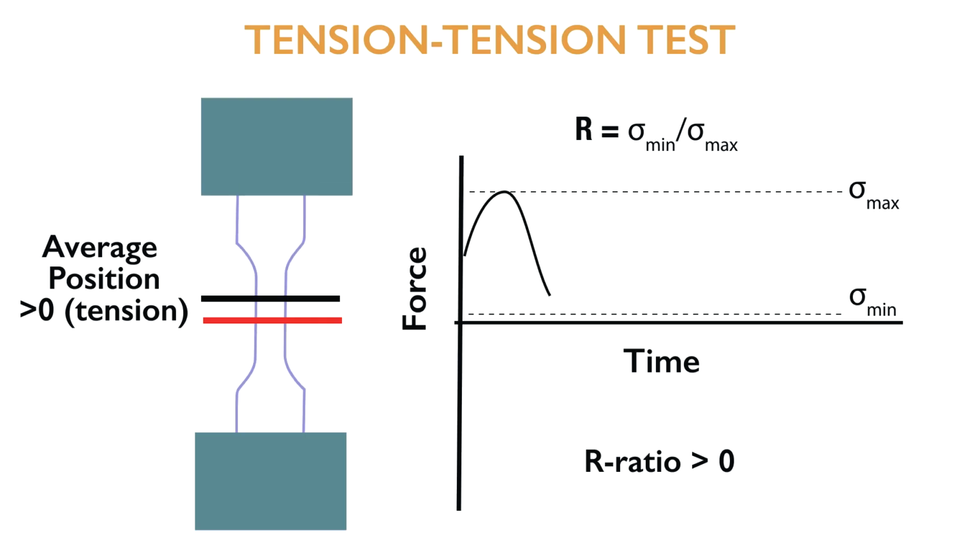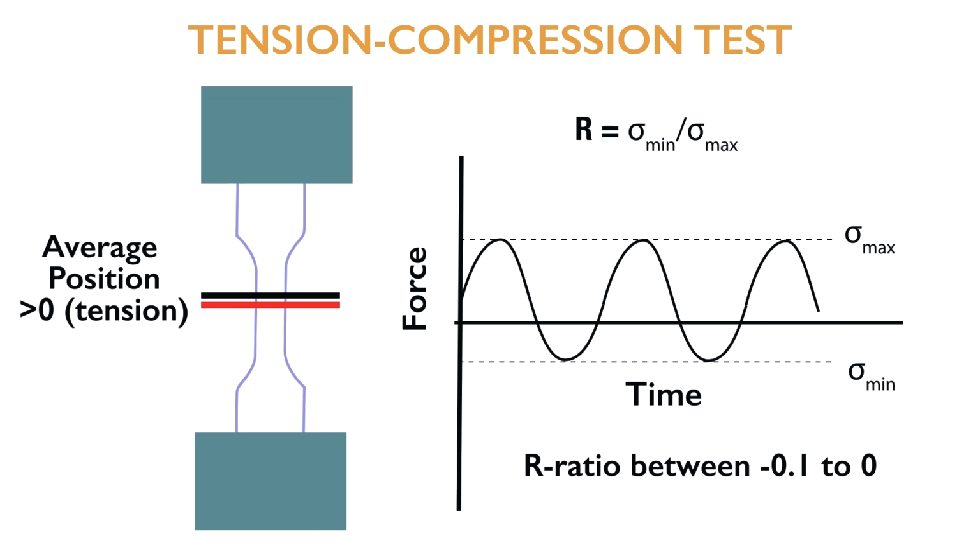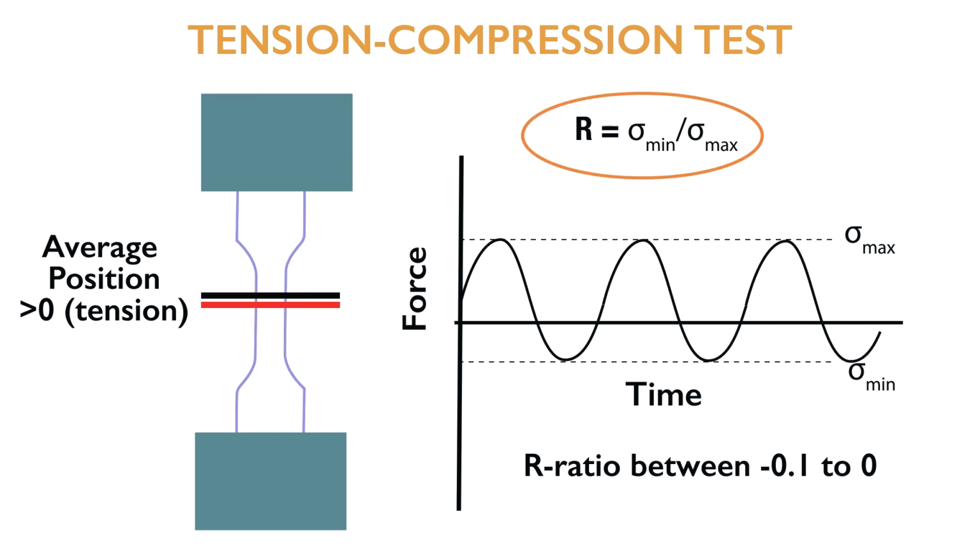Secondly, the loading conditions experienced by a material impact its fatigue performance. The main types of cyclic loading are tension, compression, tension-compression, or fully reversed. The stress ratio, which is the ratio of the minimum to maximum stress, also affects the curve. Higher mean stress tends to reduce the fatigue life. Typically for SN curve generation, a fully reversed load, that is R equal to -1, is used.